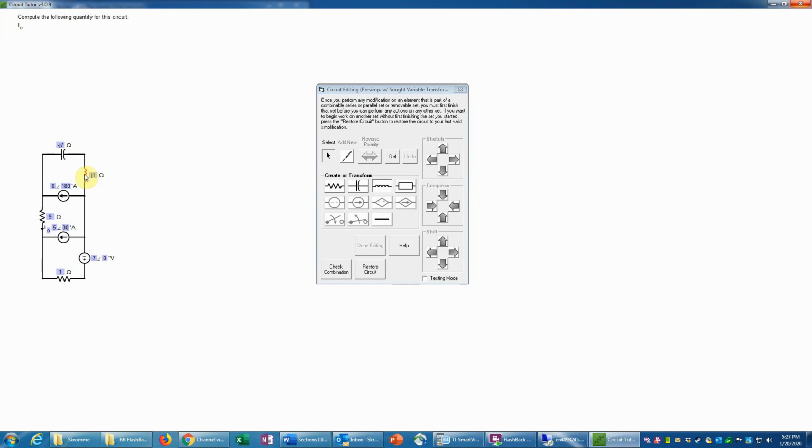And then this one we have to change to a short circuit because that no longer should contribute to the impedance here. And of course, if you change it to an open circuit, it's like you're saying neither of those things was there in the first place because the resultant would be dangling, which would have no effect on the circuit. So that wouldn't make any sense. So it has to be changed to a short circuit. So we check that, and that is correct.